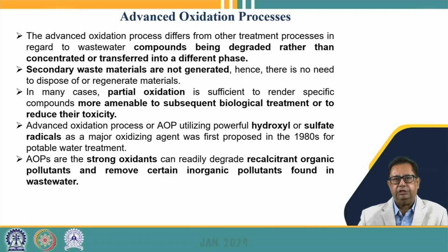So this process, that is the advanced oxidation process, differs from the other treatment processes in the sense that these compounds are degraded. Rather, in other processes they are transferred or concentrated into a different phase. For example, in an adsorption process using activated carbon or any other adsorbent, which can be put into the wastewater, the organic compounds get transferred from the liquid phase to the solid phase.